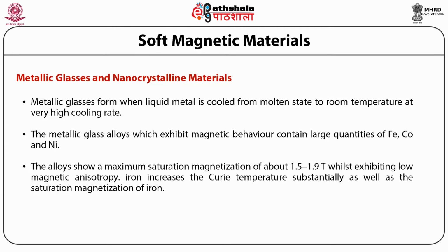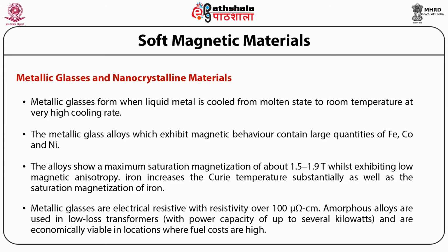The alloys show a maximum saturation magnetization of about 1.5 to 1.9 Tesla whilst exhibiting low magnetic anisotropy. Metallic glasses are electrically resistive with resistivity over 100 microohm centimeters. Amorphous alloys are used in low-loss transformers and are economically viable in locations where fuel costs are high.